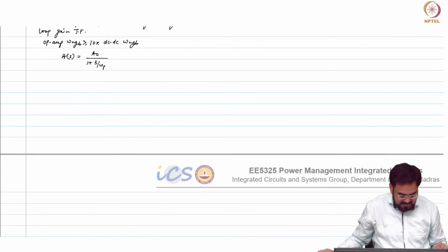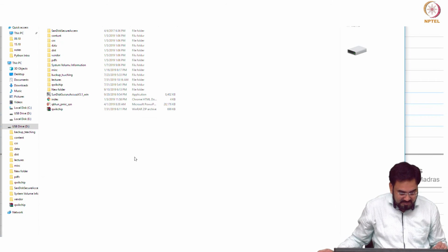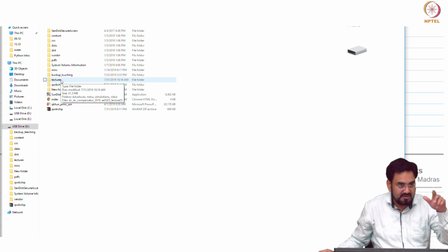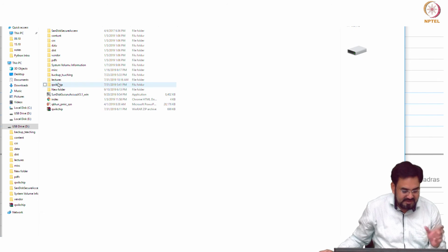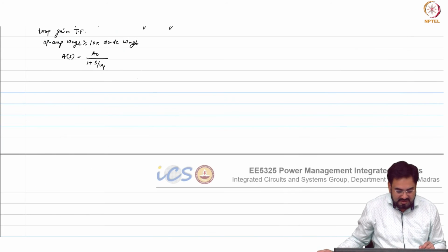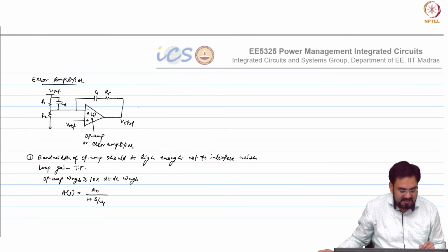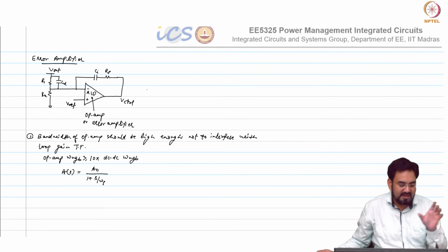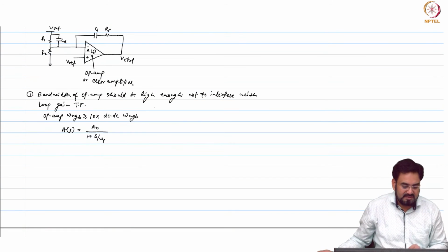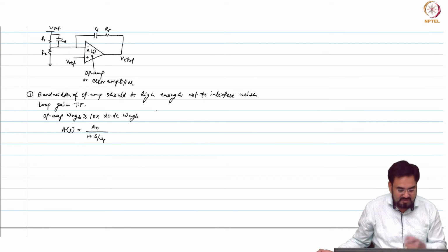So one thing I mentioned yesterday, I was talking about the resonance, so I'll just show you what happens. If you want to really see why this is occurring, you can just replace this op amp transfer function with this and then derive the compensator transfer function again, and you see how it affects the loop gain. You will see some additional resonance frequency in your loop gain. So one resonance is coming from LC, another resonance will come from L and C, and another one will come from this one due to the limited bandwidth of your op amp.